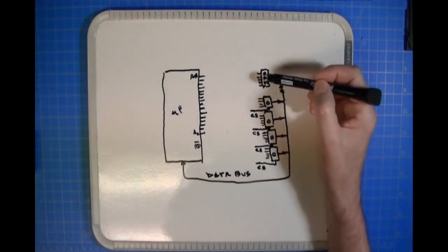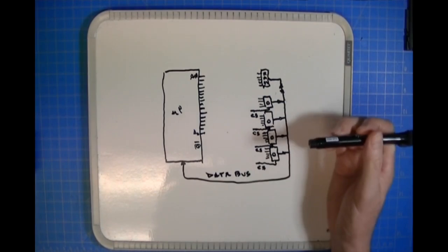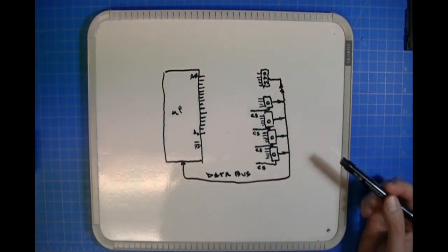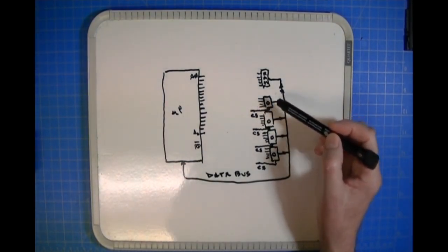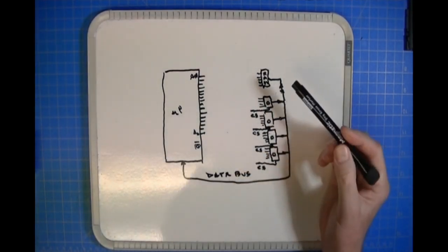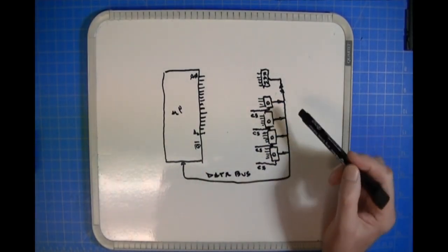The RAM has address lines too, except with the RAM, data flows in and it flows out, because with EPROMs, data just flows out. So the RAM is also going to have a chip select, an output enable, and a write input. But that's not relevant to what I'm trying to convey here. Each EPROM has a chip select line, which, once it's active, allows its data to be placed onto the data bus so that the microprocessor can read the code.